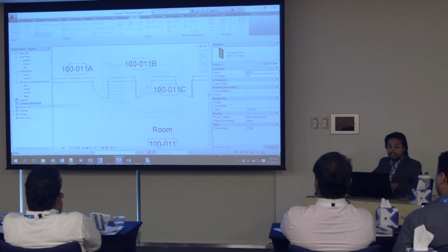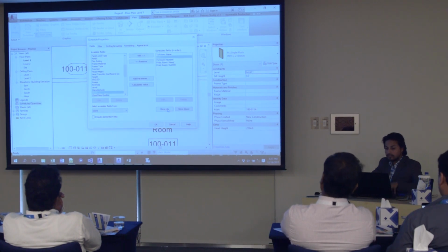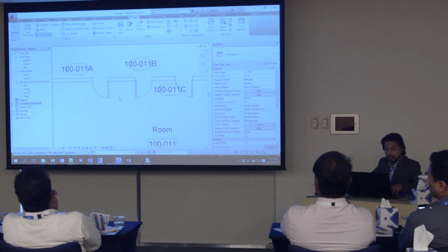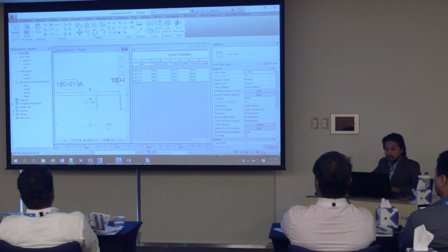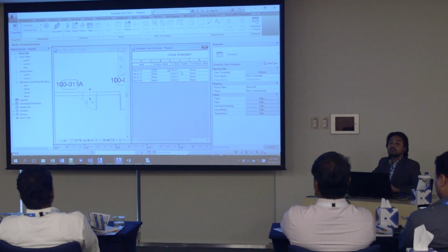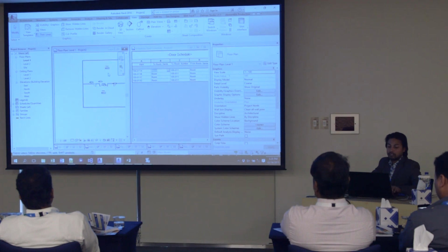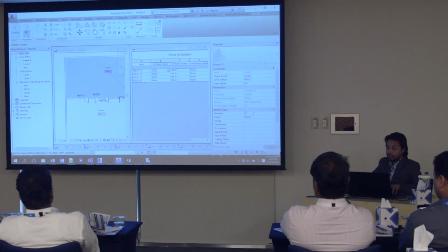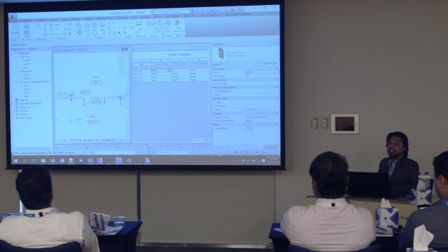But if I create a new schedule now, and let me say door, I will say to room. I'm just adding those numbers. I would say add the mark parameter as well. And it's been added. And if I window tile this, come on. All right, now this room, it has this 2-room number here. So now if I, which is 1001, but let me just change this to a different number just so we can understand this. Let me make it 500. No confusions. I go back here and then I will say change. It changed the 2-room information, as long as that room calculation point is not.